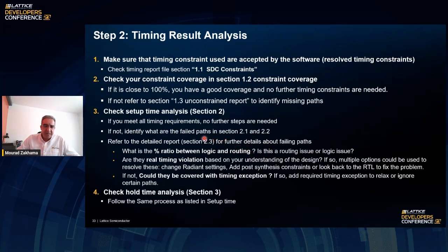If you see 90% logic and probably 10% routing, you may have an issue in terms of the number of logic levels. Maybe you need to add some pipeline registers, look at the source code, and understand what's going on there. So I think this factor is very important to have a better understanding of the timing.